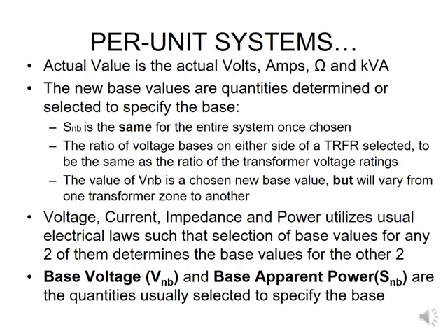Then your transmission, you would usually have it, let's say, at 132 kV or at 66 kV. And then in your distribution voltage, you could have it at 11 or 33 kV. So similarly, your base voltage would change, because it would go according to the transformer that you have in the system and what those voltages are in the transformer on your HV and your LV side, and then you utilize that voltage as your base on that side of the transformer.